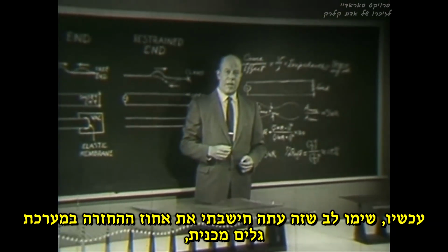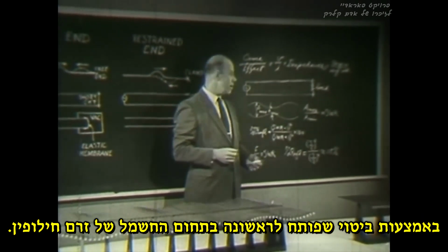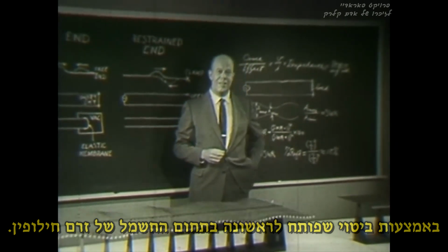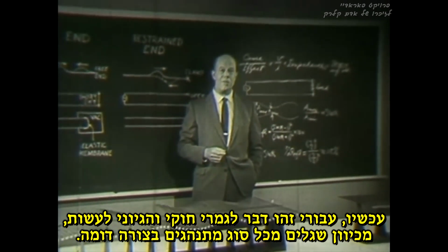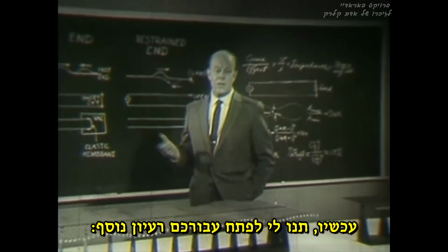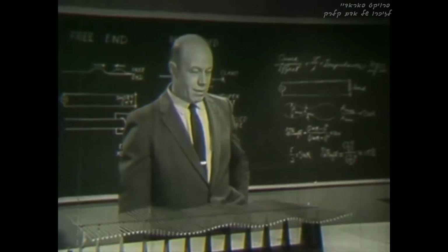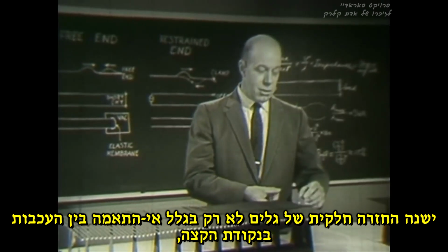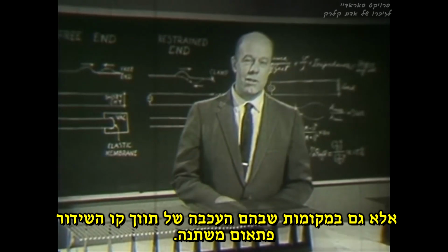Now note that I have just calculated the percent reflection on a mechanical wave system using an expression that was first developed in the field of AC electricity. Now this is a perfectly valid and logical thing for me to do, since waves of all kinds behave alike. Now let me develop for you another idea. Waves are partly reflected not only at mismatched terminations, but also at places where the impedance of the transmission medium changes abruptly.